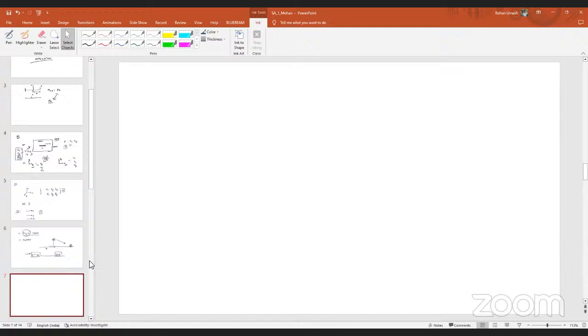Okay. And one more thing is, what is the difference between applied loads and resisted loads? Or I can say, what is the difference between applied loads and internal loads? What do you think? Will these two be the same, or will these two be different? Different. The name itself, applied load, means externally we are applying some forces on the objects. And what about internal load?